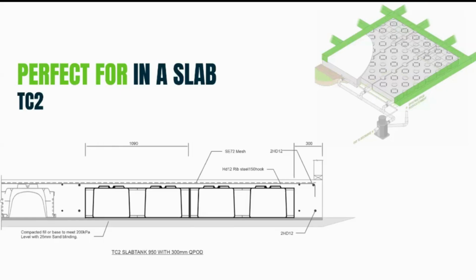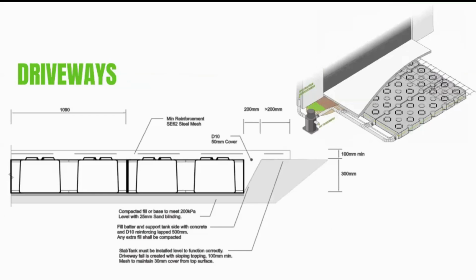The next one is specifically around trafficable areas. So if we can just make sure that we cover this question around the cover required for trafficable areas and backfill in terms of bringing concrete up to ground levels within the driveways, then we're good. So this is what we're covering here with driveways and trafficable areas.